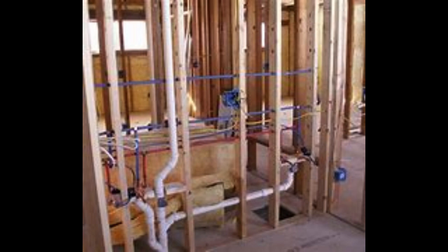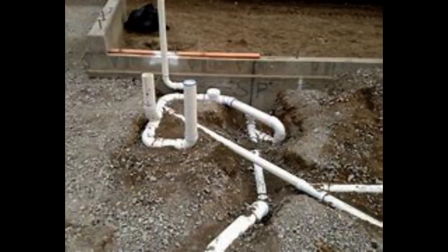2. Requirements for electric units. The inspector shall report as deficiencies: A. Performance of heating elements, and B. Condition of conductors. 3. Requirements for gas units. The inspector shall report as deficient: A. Gas leaks in water heater not associated with the gas distribution system. B. Flame impingement, uplifting flame, improper flame color, or excessive scale buildup. And C. Deficiencies in: 1. Combustion and dilution air. And 2. Vent pipe, draft hood, draft, proximity to combustibles, and vent termination point and clearances.